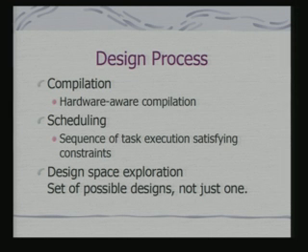The scheduling of the tasks would also mean scheduling on the special purpose hardware, if at all required. Now, all this process involves what is called design space exploration. Design space consists of alternative possibilities. Okay? So, we need to search among these alternate possibilities to find out a design which not only meets the functional requirements and satisfies the design constraints, but may be cost wise minimum. So, take an example. If I am using for an application a 32-bit processor like ARM, I can definitely meet my timing constraints.